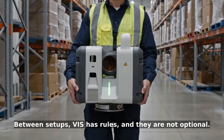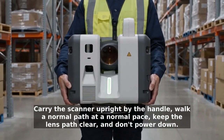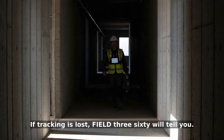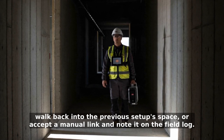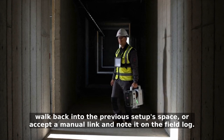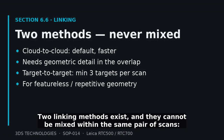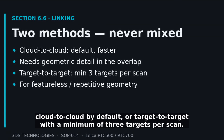Between setups, VIS has rules, and they are not optional. Carry the scanner upright by the handle, walk a normal path at a normal pace, keep the lens path clear, and don't power down. If tracking is lost, Field 360 will tell you. Do not ignore it. Walk back into the previous setup's space, or accept a manual link and note it on the field log. 2 linking methods exist, and they cannot be mixed within the same pair of scans: cloud to cloud by default, or target to target with a minimum of 3 targets per scan.